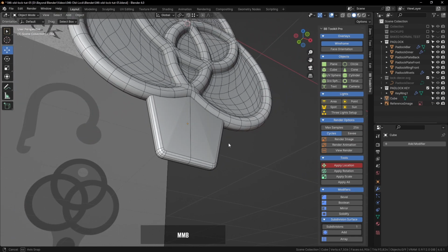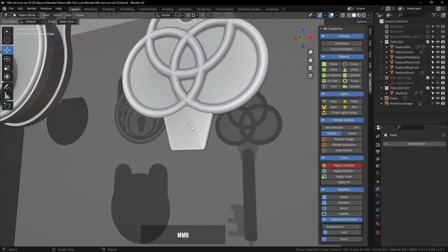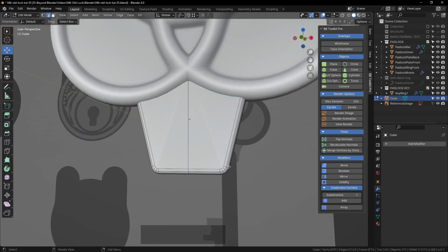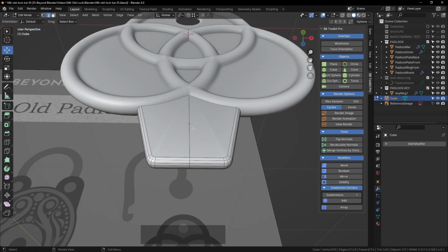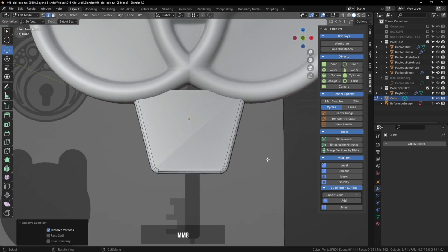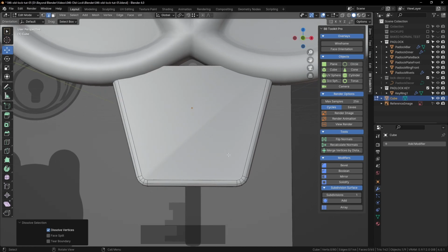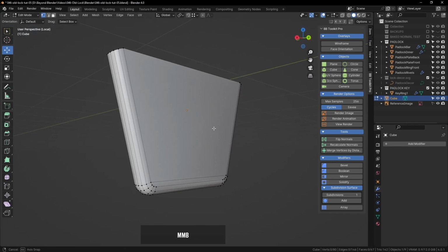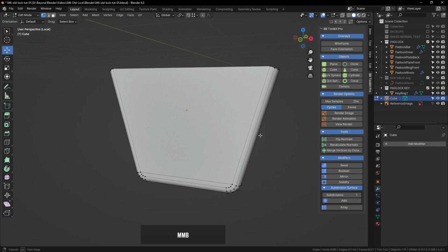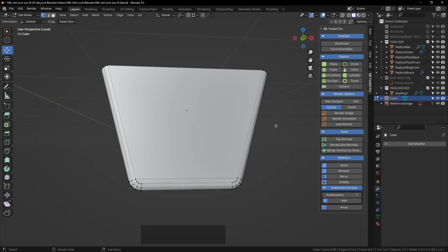That's looking pretty good. We still have some weird shading issues there because Blender's triangulated that to that top point there. So we need to fix that, and it's quite easy actually. Several ways to do this. I'm going to select that edge loop and just dissolve it for now with Ctrl Delete. So Alt click to select it, Ctrl Delete to delete it, and I'm going to select these two vertices and press the J key to join them. That will create an edge between those, and that will stop those triangular faces shooting upwards vertically. So that looks a lot better now.